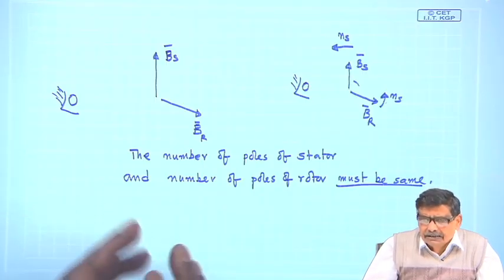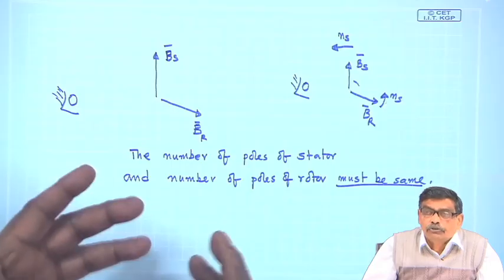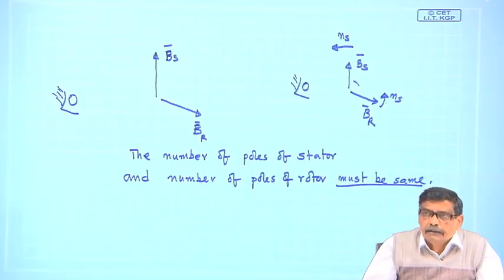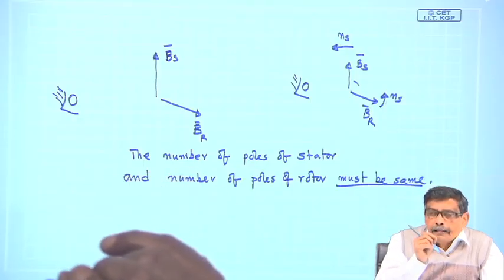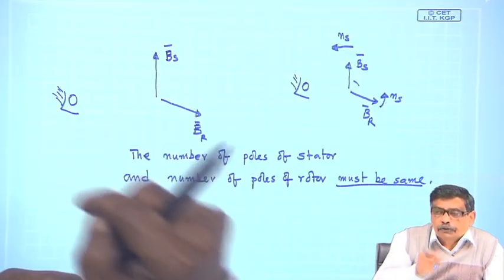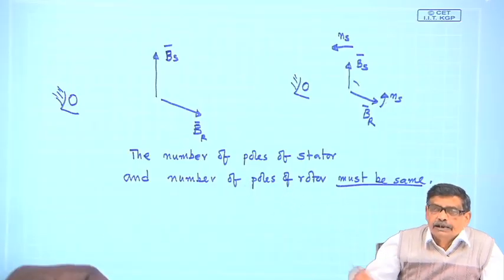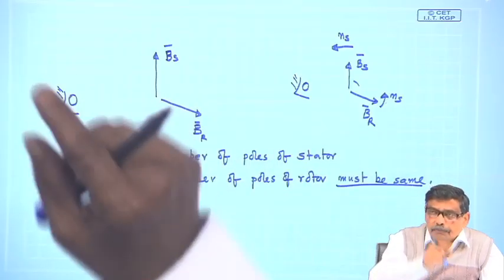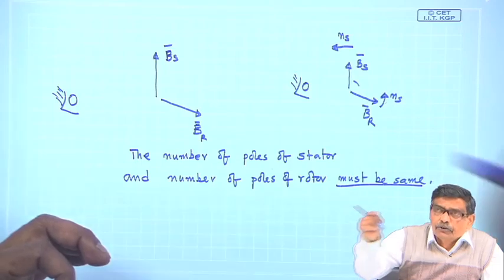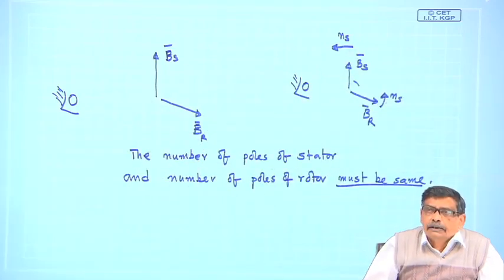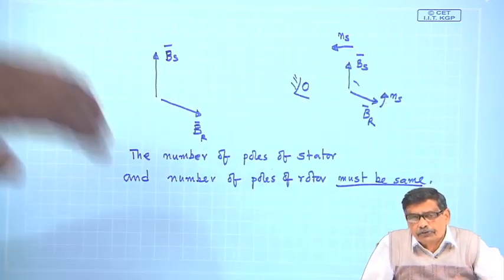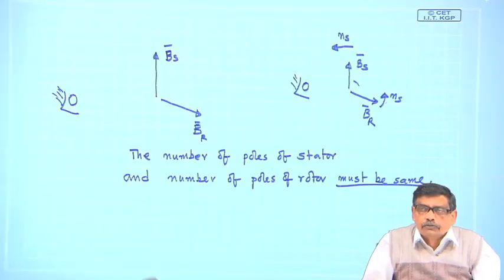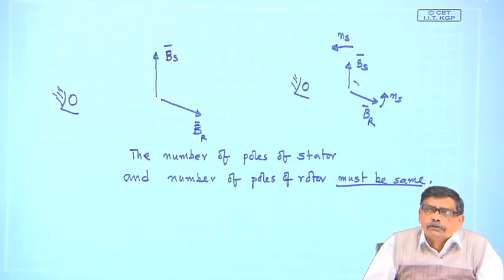There cannot be a situation where 5 poles are created by a stator, because of the lines of force. You must give a sink for a north pole: lines of force cannot just terminate, they must close their path via a south pole. Lines of force must enter a south pole. So, the number of poles cannot be odd, it is always even.